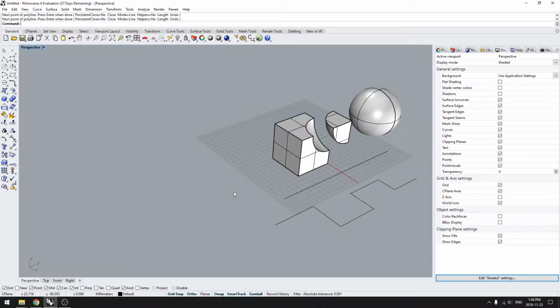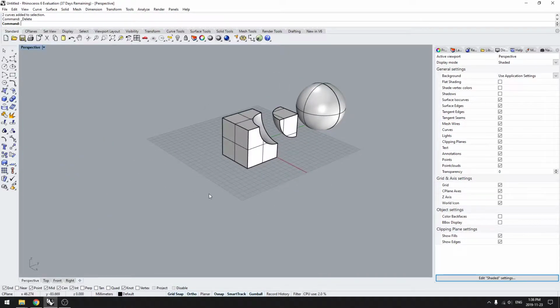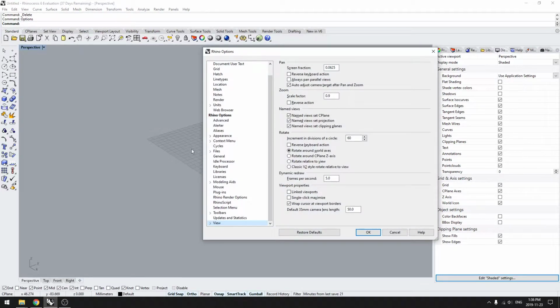With aliases, you can actually just type A, and you get the line command. You type double A, and you get the polyline command. And you can do this for any command. And the best part is you can actually also put commands together to make macros.